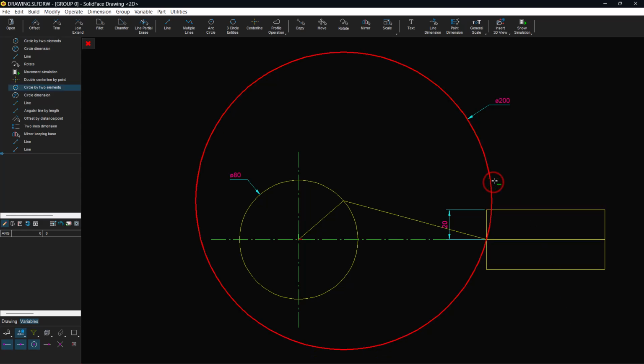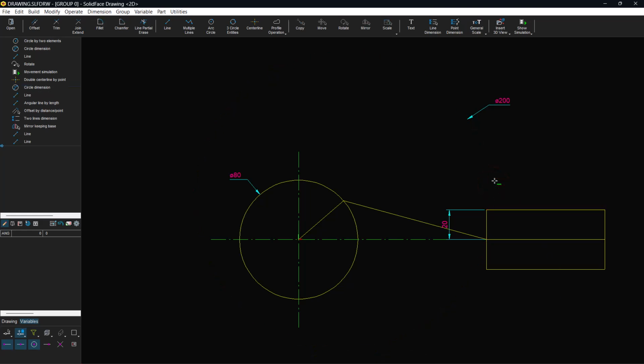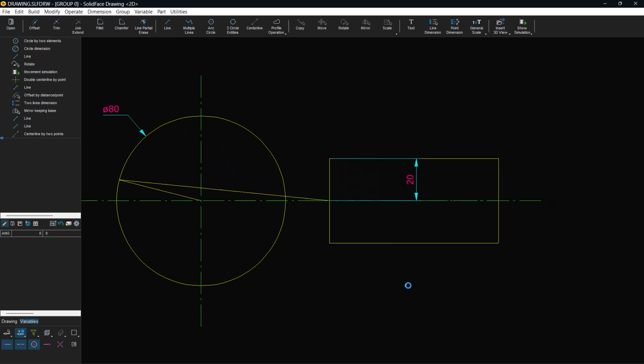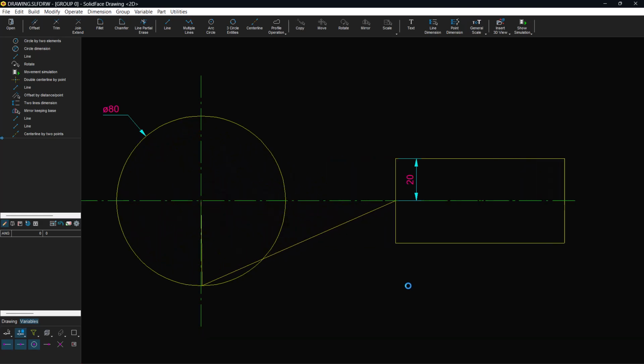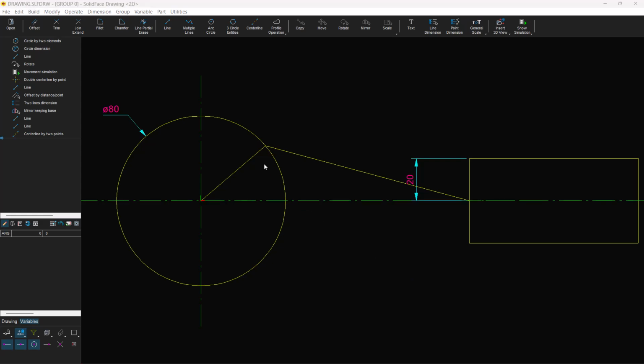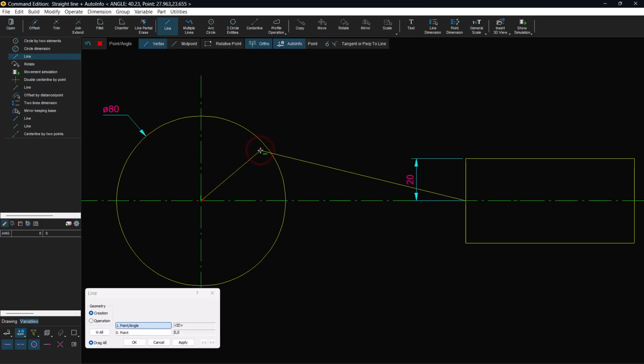Erase the reference circle used for the connecting rod construction and the piston baseline. Creating a center line. Testing. Remember that the hand crank line was created at a point on the circle between 0 and 90 degrees. In that position, it was easier to show the simulation geometry construction. Now, once constructed, edit the hand crank line so its endpoint ends in the circle quadrant with angle 0.